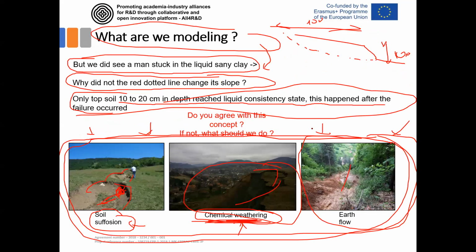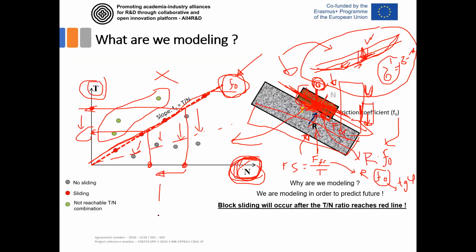That's what we have in the soil. Numerically, it can be defined like this. If this is N force, this is T force, the slope of this is phi, and this is cohesion. Of course, since this is force, this will be some measure of cohesion, since the SI unit of cohesion is kilopascal. So this is resistance to sliding when the N force equals 0.